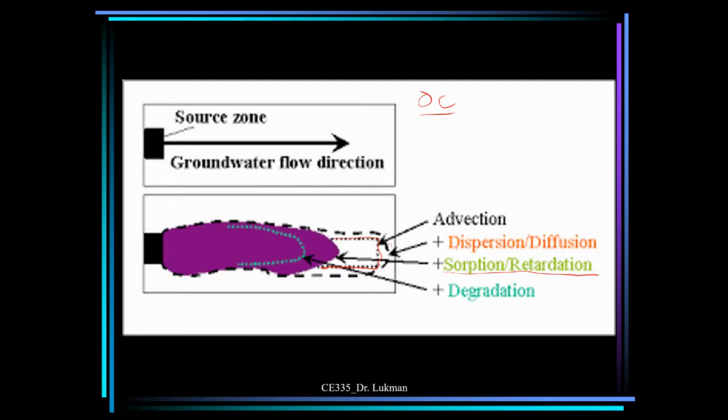All soil has what is called organic content, which is obtained by heating the soil in an oven at a temperature above 100, like 105, for some hours. You measure the weight before and after, and the difference is usually around 3%, maybe 3 to 5%. It depends on the soil type, their origin and all that.